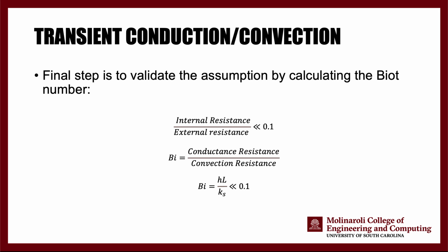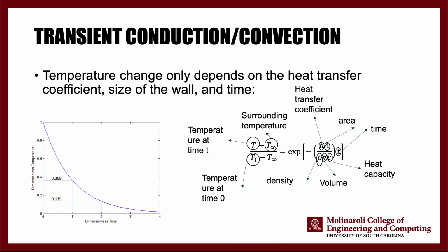Okay. Well, in the beginning of this, we said there is a limit to the validity of the assumption we made about the convection scenario. Where is that limit? And that limit shows up in the Biot number calculation. So the validity of our assumption that we made, and the assumption was the conduction is negligible. We don't need to include conduction in analysis, which helped us to come to this equation.